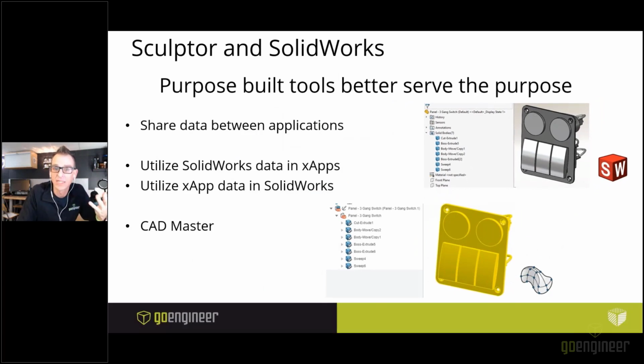Now what it does is it manages what we refer to as the CAD master. It shows us exactly who happens to be seeing this, what the originating product was for design, and it's going to go ahead and control where those edits can be made if and when edits happen. But like SOLIDWORKS parts and assemblies and drawings and the associativity that they have, we also have a great element of associativity between any of the 3D XML data on the platform and native SOLIDWORKS data. It's really a beautiful thing to watch it happen.